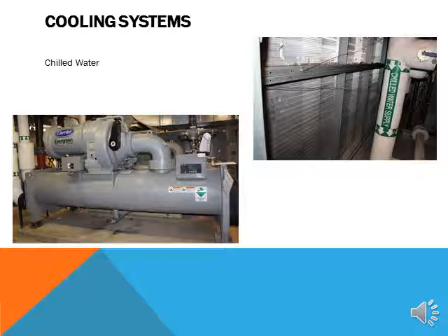A chiller also has a condenser bundle which takes water, circulates it through a cooling tower to reject the heat to the outside, then bringing that water back to the building to be recirculated through the condenser to maintain the condensing temperature. These systems can go from small chillers to very substantial chillers or multiple chiller systems to maintain the building's cooling load.